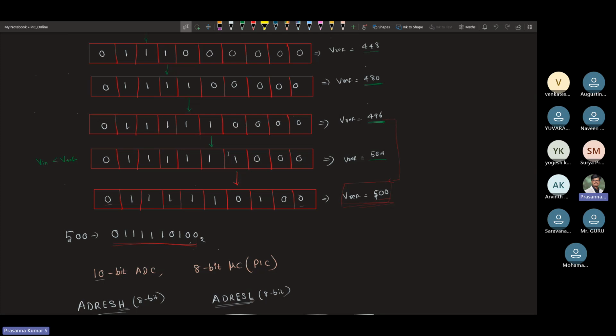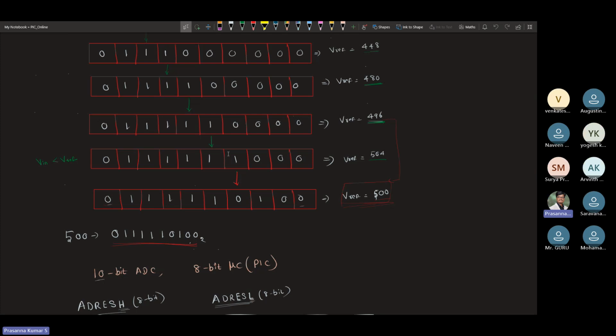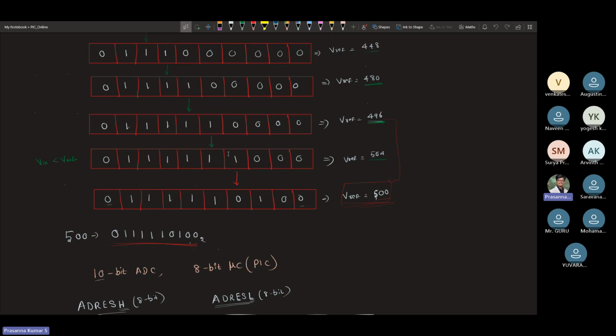So we will go for the interrupt method. Once you get an input, your interrupt will automatically start this conversion in the background. During that period, your CPU can do some other operation. Once this conversion is completed, then you will print it somewhere, whatever it is. And also DMA, same method. DMA, as I already said, is direct memory access. So your analog device will directly access the memory and do this conversion process.